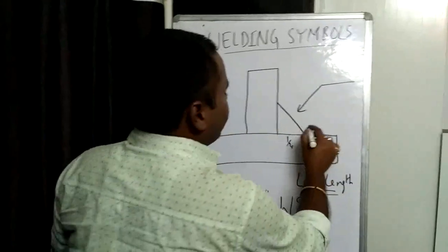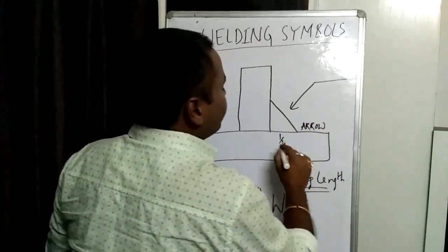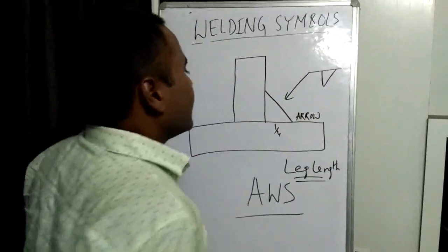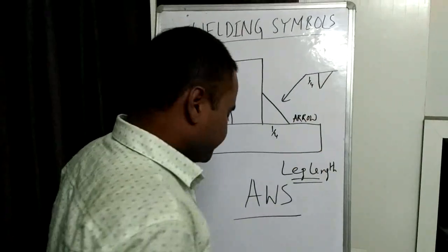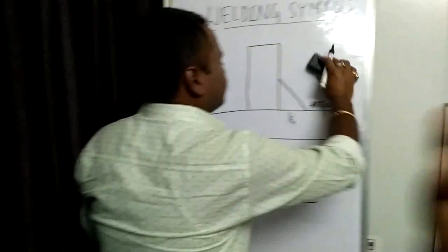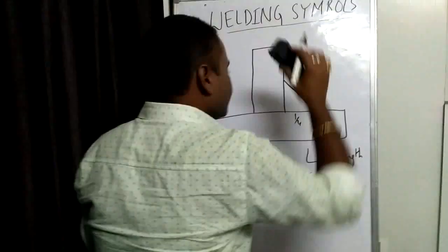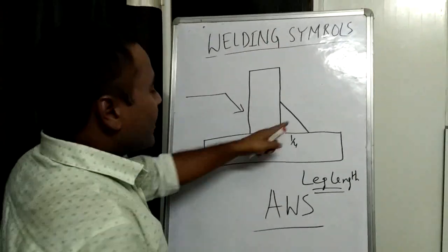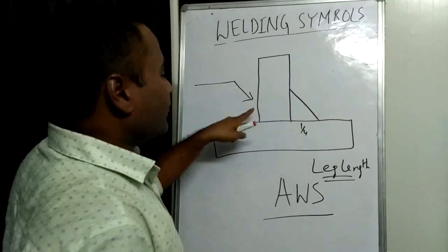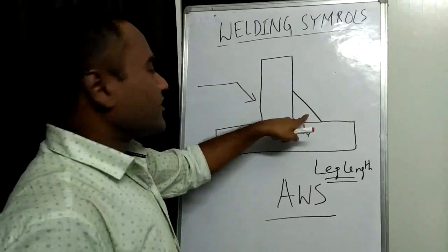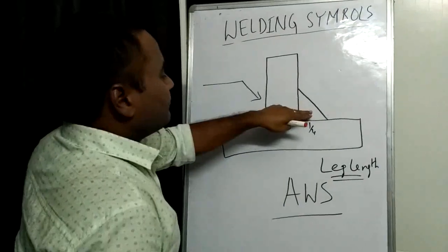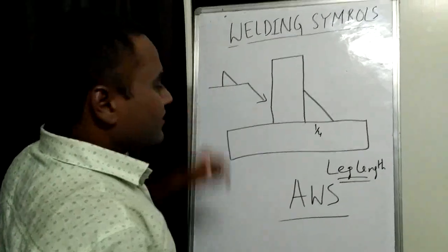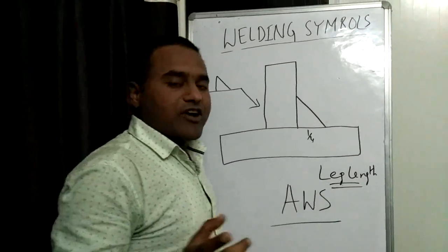then similar, this is our arrow side. So for arrow side welding, we have to provide the symbol below the reference line, and the leg 1/4. Now if I put the symbol over here, and welding has to be done on the opposite side, that is the other side. Now this side has become arrow side and this side has become other side. So for this, the fillet symbol shall be given above the reference line. Now we will take an example of ISO.